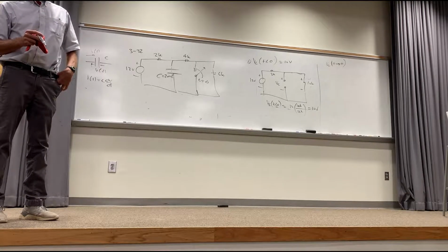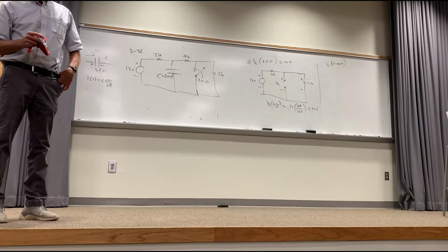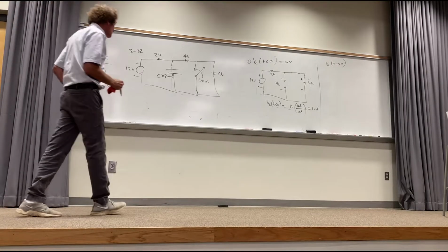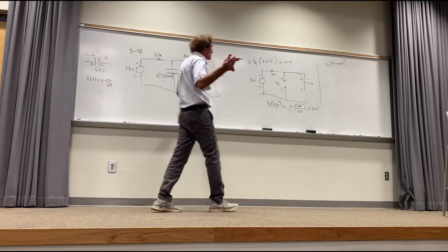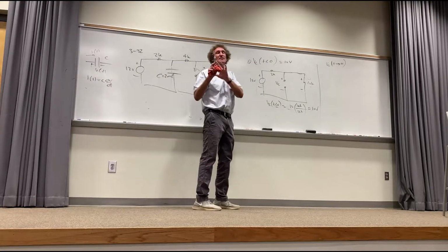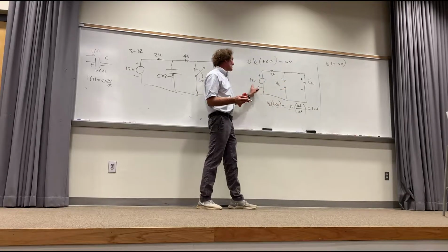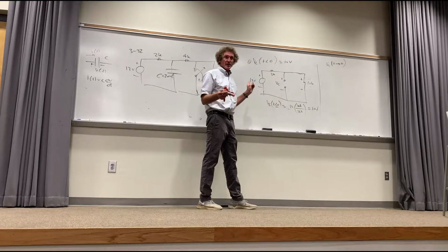So this is kind of similar to her question. You could also solve for the voltage at t less than 0 by just finding the current in that circuit and doing 12 volts minus I times this. Listen, there's a lot of ways. This is the easiest. But if you want to find the current flowing here, that would be 12 volts over 12K, right? 1 milliamp.